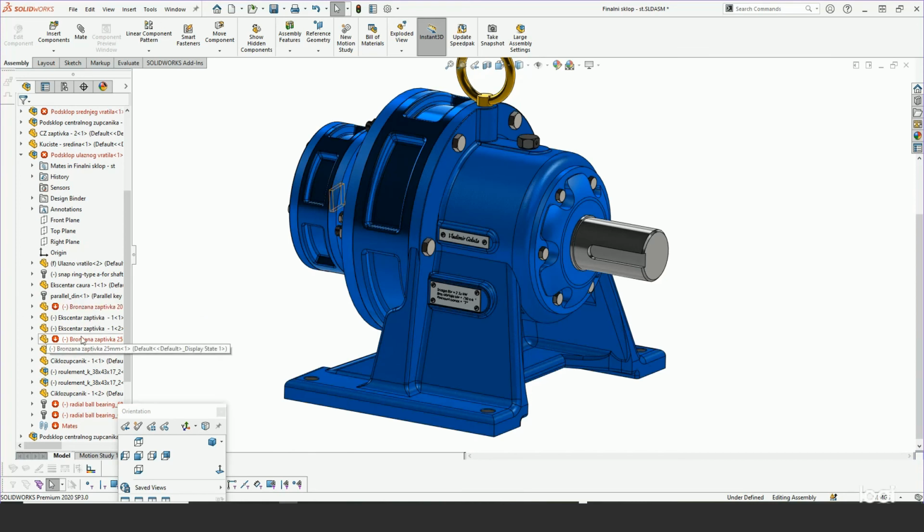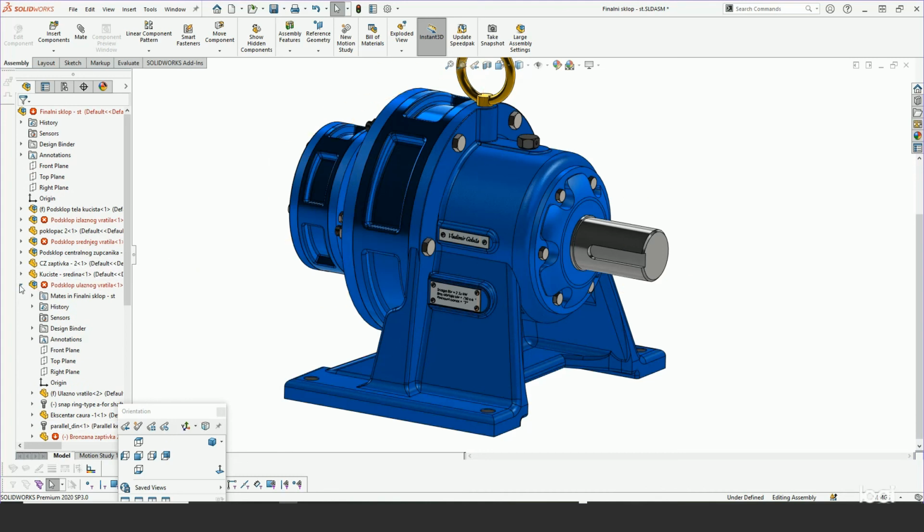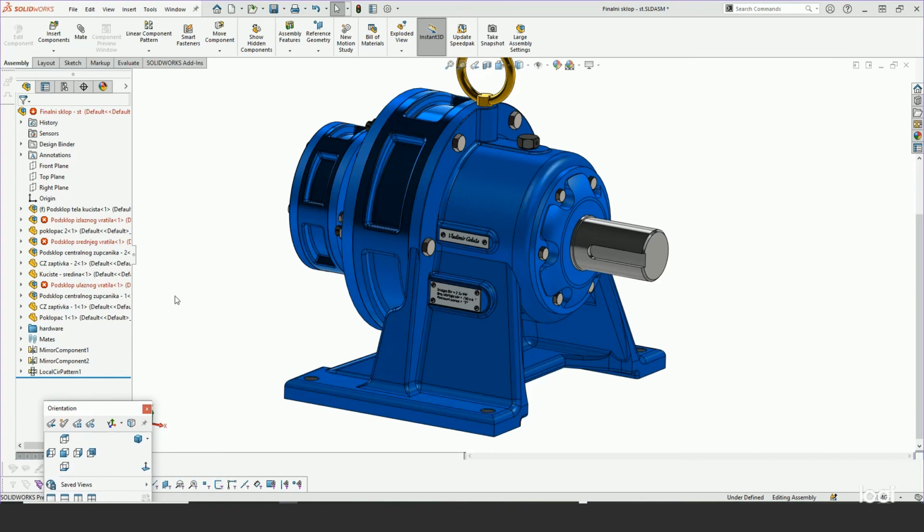I could spend a lot of time traversing through the tree to figure out what's going on here. But one thing I do as a tip when I'm faced with this kind of issue is I'll use the isolate command to help me out. Now, we know about the isolate command for modeling. It's just fantastic. When you have many bodies or many assemblies, you can use isolate to reduce down the ambiguity of your model. But I find it really useful for repairing mates also.